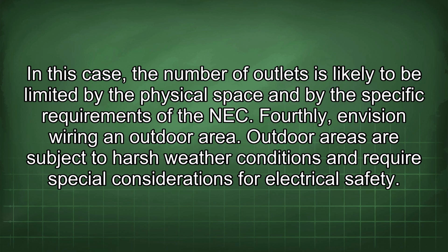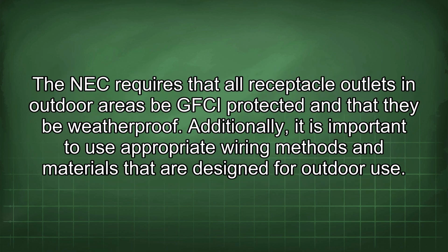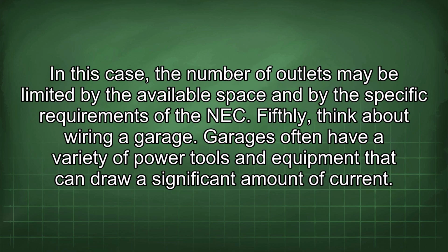Fourthly, envision wiring an outdoor area. Outdoor areas are subject to harsh weather conditions and require special considerations for electrical safety. The NEC requires that all receptacle outlets in outdoor areas be GFCI protected and that they be weatherproof. Additionally, it is important to use appropriate wiring methods and materials that are designed for outdoor use. In this case, the number of outlets may be limited by the available space and by the specific requirements of the NEC.